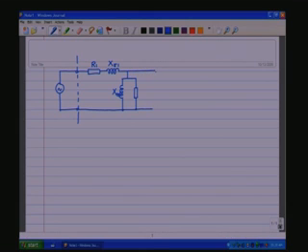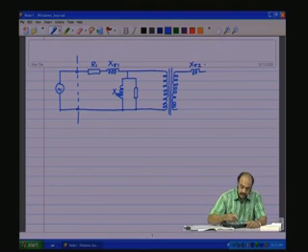The magnetizing reactance and the core loss component are now connected to the ideal transformer, like this. There is a core with ideal characteristics, the secondary of the ideal transformer, which is connected to the leakage reactance on the secondary side due to the leakage flux of the secondary ampere-turns.